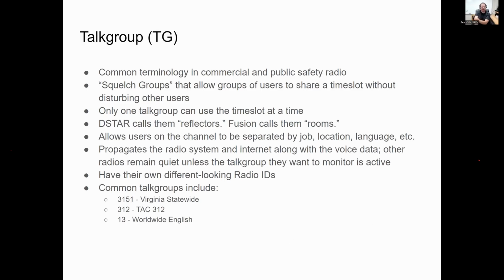I mentioned talk group, so here's a good time to introduce it. Common terminology for a channel, sometimes called a squelch group. We used to use PL tones to differentiate talk groups on a repeater. We are happy with one PL for everybody to use, but in the commercial world, in earlier years, you would have many different companies sharing a single repeater with different PL tones that operate as their squelch group. So you'd be sharing the random access repeater in that mode. So that's where this came along from.